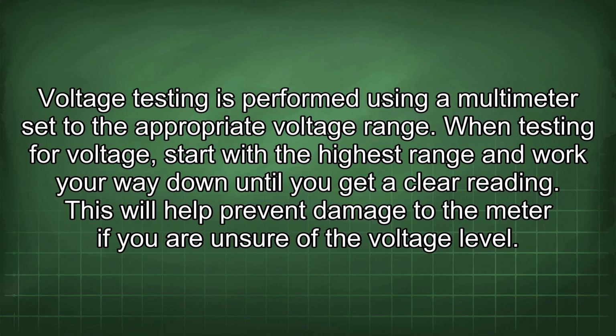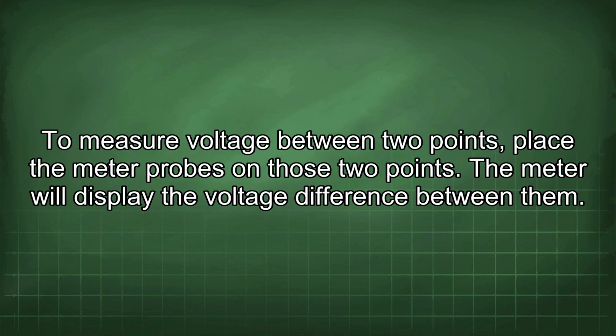This will help prevent damage to the meter if you are unsure of the voltage level. To measure voltage between 2 points, place the meter probes on those 2 points. The meter will display the voltage difference between them.